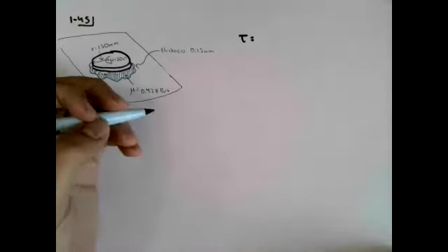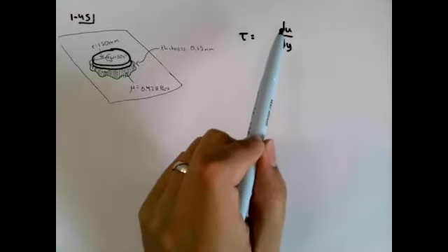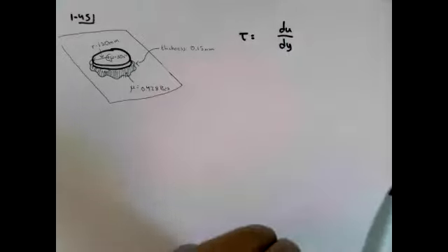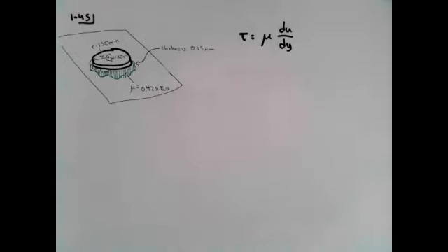So if it's a viscosity problem, I'd like to point you to Newton's law of viscosity. Newton's law of viscosity tells us that the shear stress applied in a fluid is proportional to the strain rate. Now, in lecture for week number 2, I explained how the strain rate can actually be calculated by taking the derivative of velocity with respect to depth, and that the factor of proportionality is what we call viscosity or dynamic viscosity. So, given this information, we are asked to find the torque, okay?